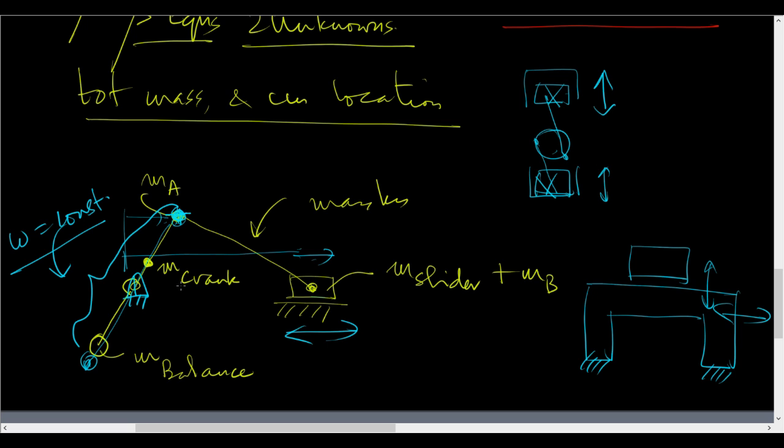What I meant to say is, if I leave some unbalanced mass over here or over here or wherever it is, you see, if I leave a negative unbalanced mass here, that is exactly the same as putting a positive unbalanced mass here. Let me have a negative unbalanced mass here. That negative unbalanced mass has this acceleration which matches this acceleration. That negative mass can be made equal to this one, and then what will happen is actually just this vertical part will be there.